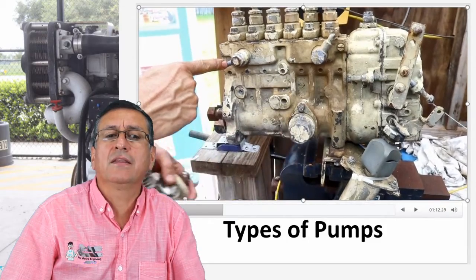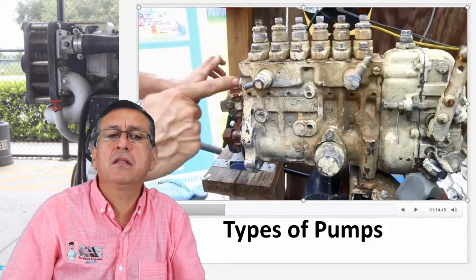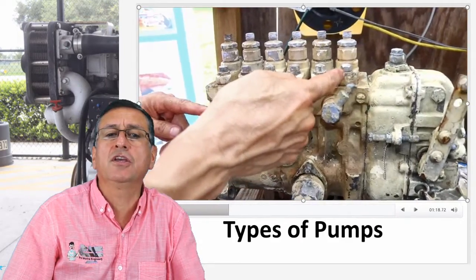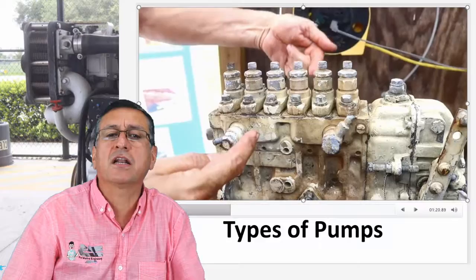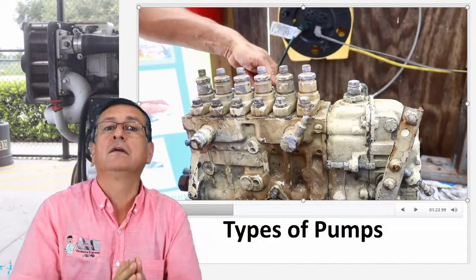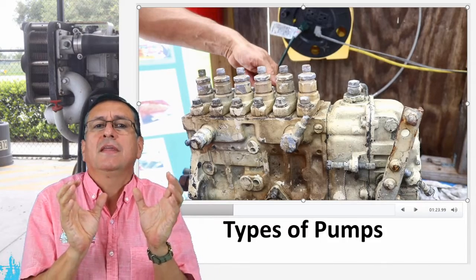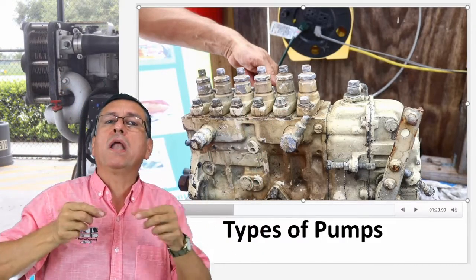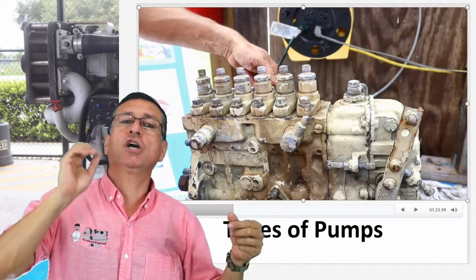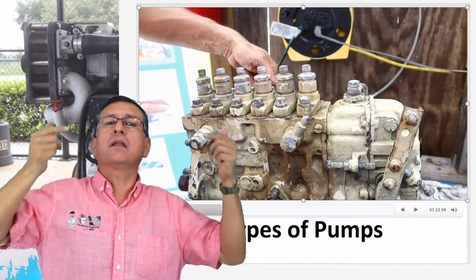Okay, the input enters each small cylinder, each plunger, and on the other side the return goes over there and back into the fuel tank. It's clear? We have exactly the same as in the big engine: one intake manifold, or supply manifold, or discharge manifold, and one return manifold.